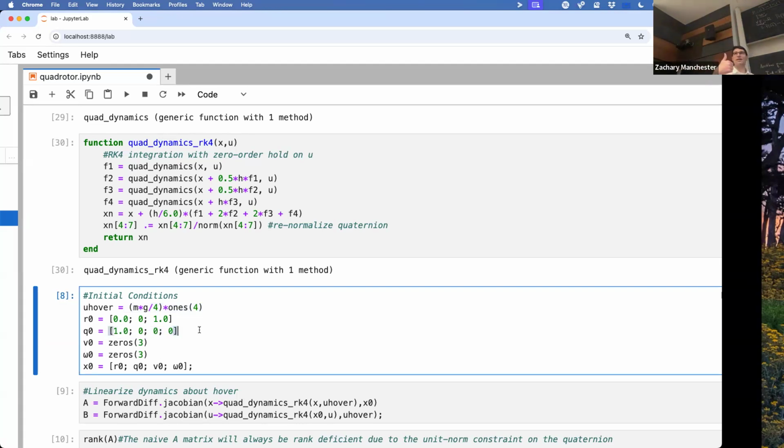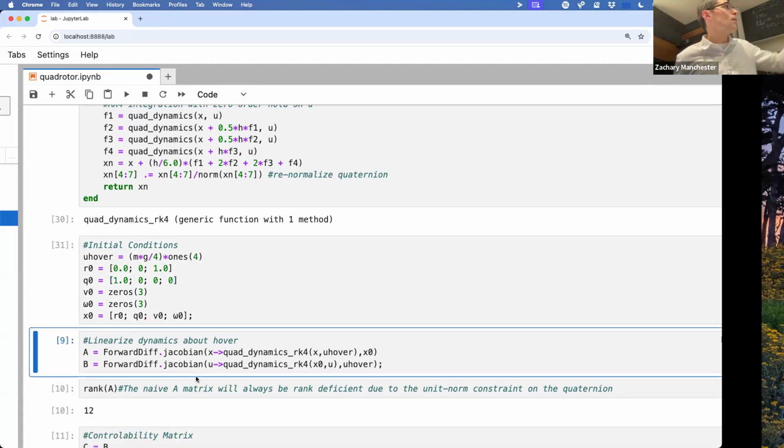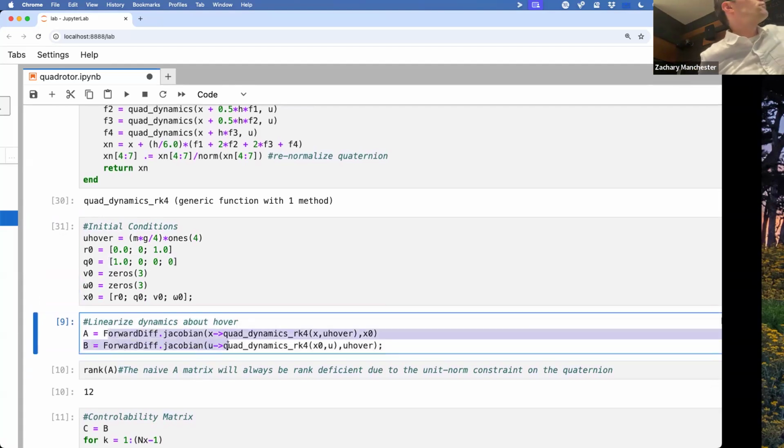One other thing to be careful of here: I'm assuming a right-handed coordinate system on the drone with Z up, but the standard coordinate frame for airplanes actually has Z going down through the floor of the airplane because of pitch, roll, yaw, it turns out. So be careful with this. You'll very often see upright is actually upside down from what you might think. If you use a lot of the simulators, that's a common airplane convention because it makes the XY body coordinates line up with pitch and roll in the right-handed sense. Then if you do the right-hand rule, it ends up with yaw being aligned with Z through the floor. So be aware, I'm doing it this way. You'll see this in a lot of drone applications, but a lot of aero stuff that comes from airplanes uses a different convention where Z points to what you would expect to be down. So just be careful.